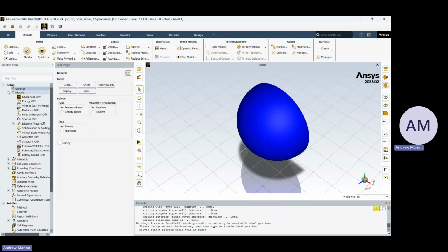But if you don't want to do the flow over the entire aircraft, and you're more interested in the minute details, like adding a winglet and changing its angle, and you only simulate a small section of the aircraft, then it might come into play more, because gravity is a small detail. Besides that, generally not going to use it.